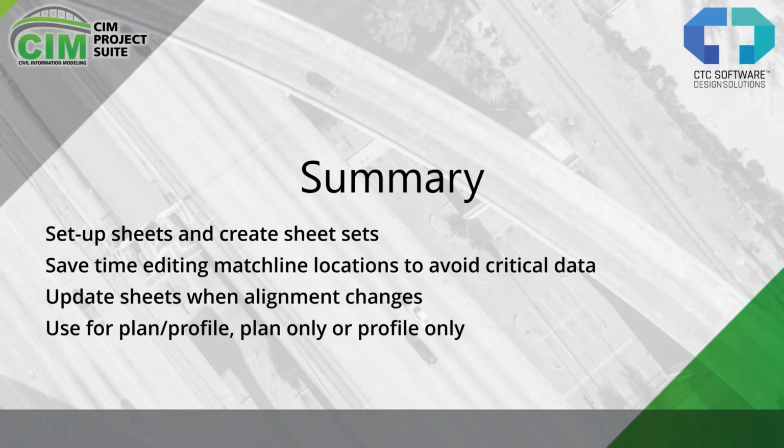So we don't have to run them and then see that it went through a manhole, or if the storm or sanitary changes and now they've gotten in the way, we can just simply go back and update them and it will take care of that. That can be used for plan and profile, plan only, or profile only, however you want to do that.